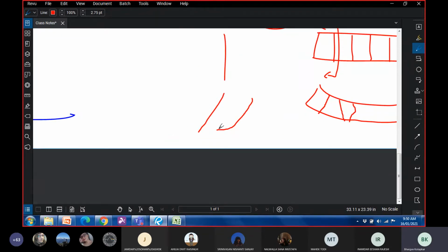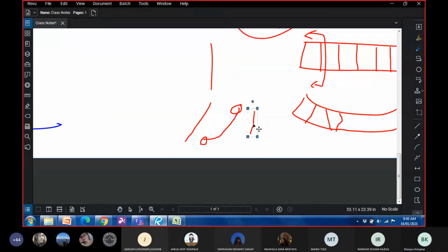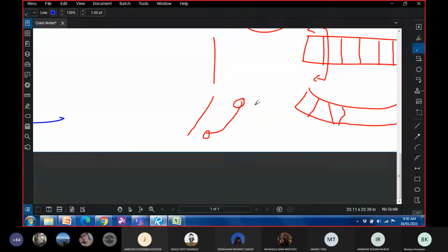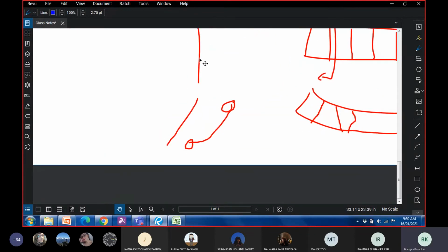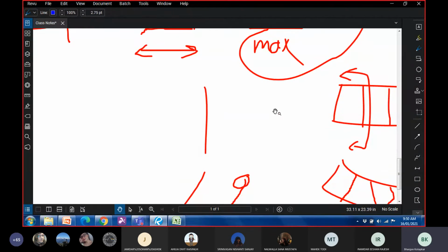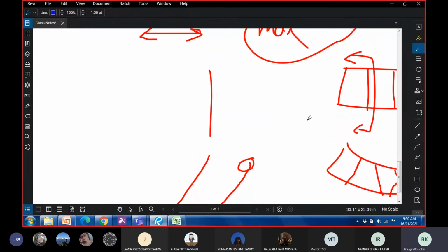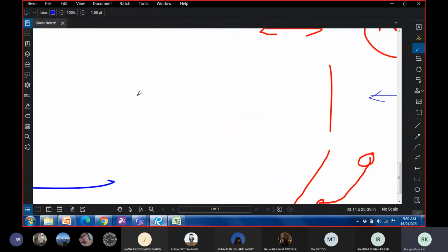What this would imply is that the tensile strain is higher than the compressive strain. If it had gone the other way, the other case would be that the compressive strain is higher than the tensile strain. In that case, you would expect a distortion in this section. Just assume that this line means a cross section. So if you look at it from this side, it will give you a cross section.